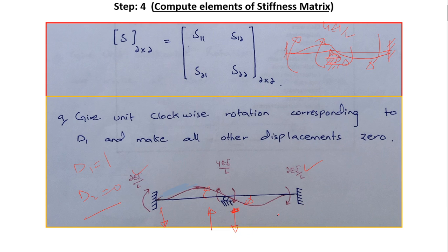Now it is forming an anti-clockwise movement and resistive is applied. Next step is balance this with upward, and the magnitude of these loads are always 6EI divided by L square, where EI depends upon the spans and L is the length. They may differ because this is about 30 feet and this is 20 feet. However, the formula is same, 6EI by L square.